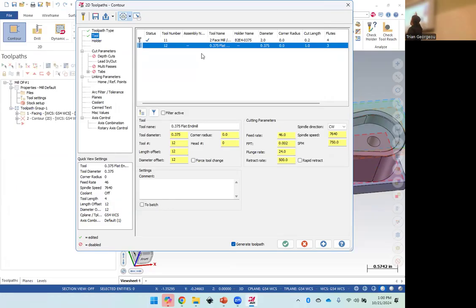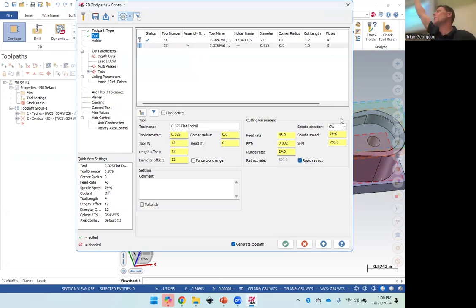If you modify them, you can right click on them and reinitialize them from the library if you had to. Now, I always click rapid retract, but the retract's probably faster than the 5% rapid here. It's up to you. But I would always, just for now, hit rapid retract so it pulls out G00 and Z whatever it does to the clearance height. Cool. That's one thing I didn't click on the last toolpath. I forgot to tell you about that.